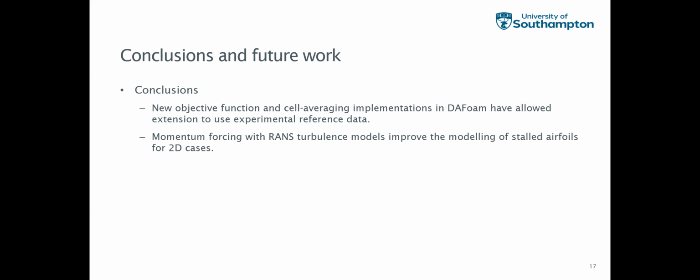So seeing as data-driven turbulence modeling is beneficial for those who do not have really an expertise in the physics, in actual physical modeling, we wanted to come out with some framework which can be easily used. And seeing as how DAFoam is helpful in that sense, we tried to merge this forcing in the momentum equations with the discrete adjoint tool DAFoam, and we saw that these are giving us quite good results for higher Reynolds number cases, and currently it's being tested for 3D.